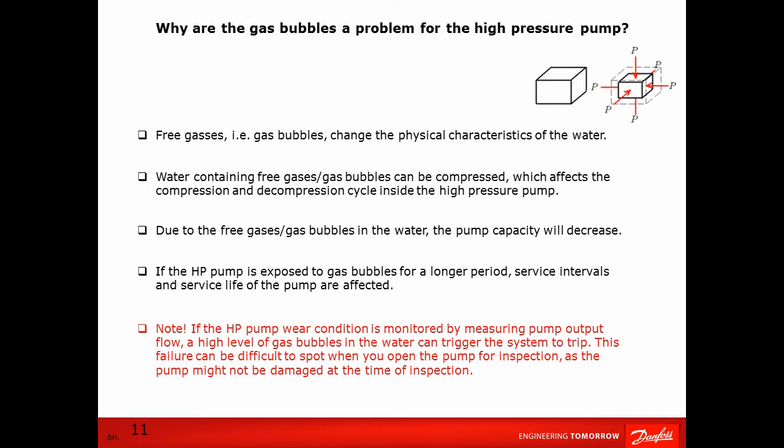Why do the gas bubbles cause problems to the high-pressure pump, you may ask? Here is the answer. The gas bubbles alter the compressibility of the water, and high-pressure pumps, also known as positive displacement pumps or axial piston pumps, are designed for non-compressible fluids.